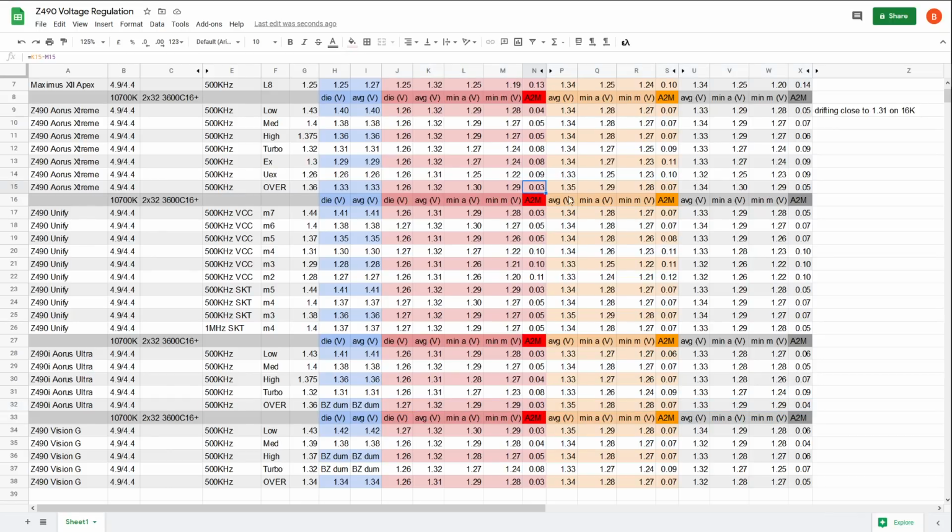0.03, 03, 07, 07, 05, 04. Oh, it looks like it does slightly better over here. And the VRM differences are pretty significant between these two boards. This one uses a bunch of doublers to get up to a 16 power stage Vcore. This doesn't have any doublers. It's just a straight 8-phase. They both use 90 amp smart power stages. This has only POSCAPs for its output filtering. The other has a bunch of through-hole polymers, and then also a bunch of POSCAPs before the socket, and then some inside the socket.